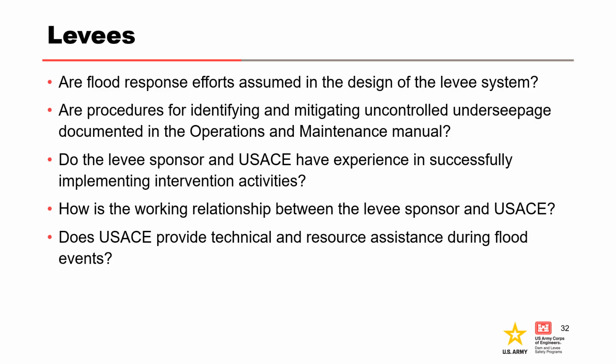To wrap up, I want to have a short discussion on intervention as it relates to levees. Intervention is part of the design for many levees, so there are some questions that we should ask when evaluating this node for a levee system. Are flood response efforts assumed in the design of the levee system? Are the procedures for identifying and mitigating uncontrolled underseepage documented in the O&M manual? Does the levee sponsor and the Corps have experience in successfully implementing intervention activities? What is the working relationship between the levee sponsor and the Corps? And does USACE provide technical and resource assistance during flood events? These are all considerations that should be taken into account during risk assessment of a levee.